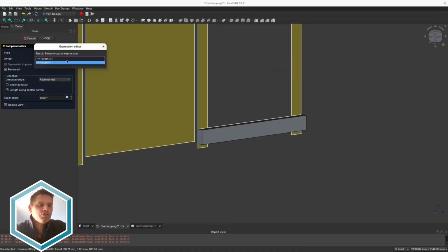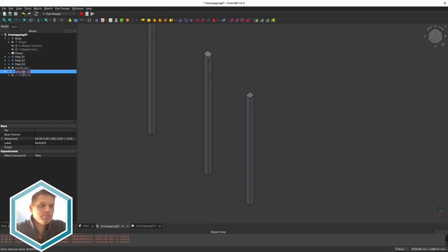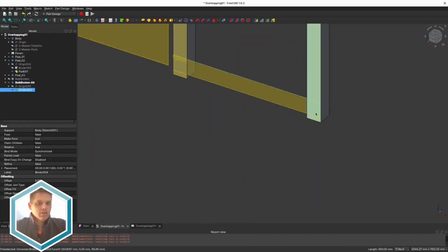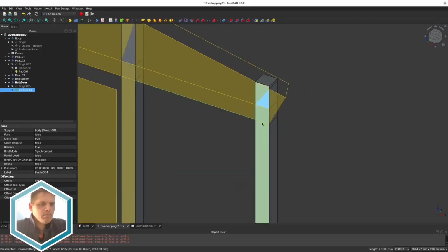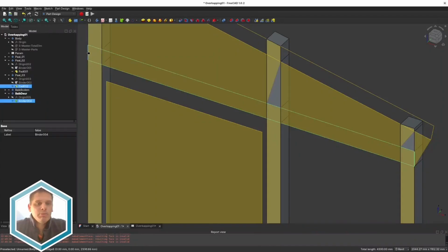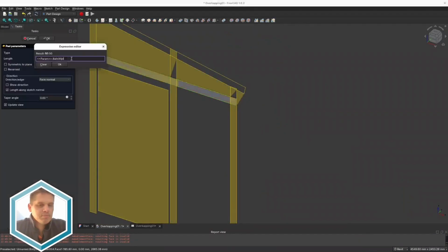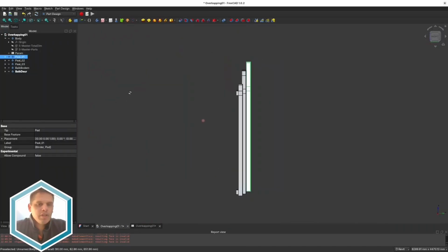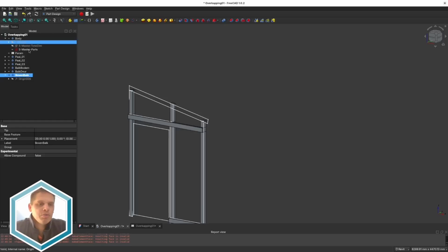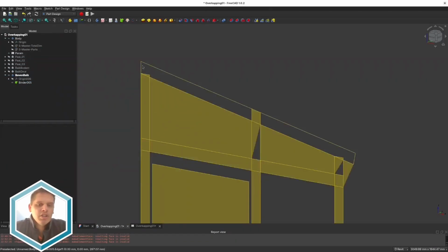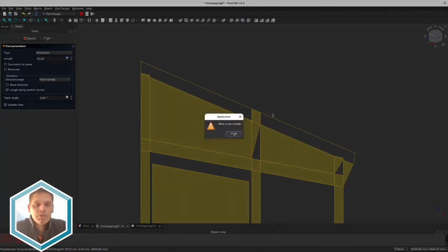So far I've done 3 poles in this video up to now. Now I'm doing the beam at the bottom. Another option for the beam at the bottom. And the beam above the door. One thing I could have done better in the shape binders, or in the master sketch to begin with, is to disable draw faces, because you see these weird faces everywhere that don't really need to be there at the moment.